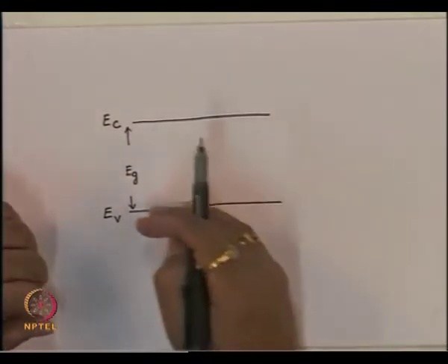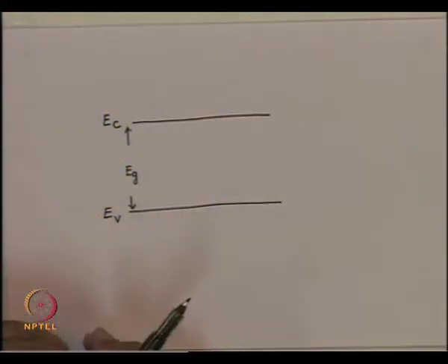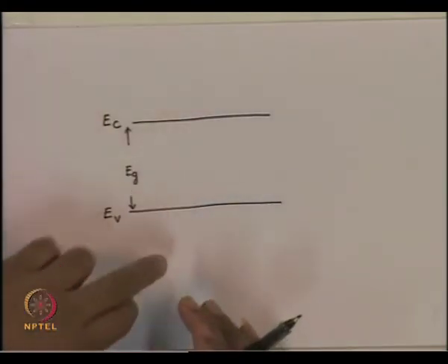The electrons and holes are not sitting on the edge of these band gaps. Essentially, we have a distribution of electrons and a distribution of holes in the conduction and the valence band. And then any electron in the conduction band can recombine with any hole in the valence band. So, what you are saying is there is no preference of any particular electron in the conduction band getting combined with a particular hole in the valence band. So, once the electrons and holes are given, there is an equal probability of any electron getting recombined with any hole. With that assumption, one can ask a question: if there is a distribution of electrons in the conduction band and a distribution of holes in the valence band, and if any electron can recombine with any hole, what kind of spectral distribution would we expect from this semiconducting material?